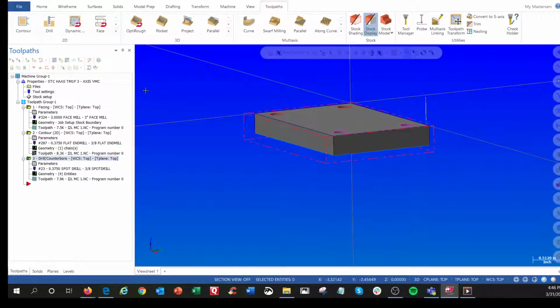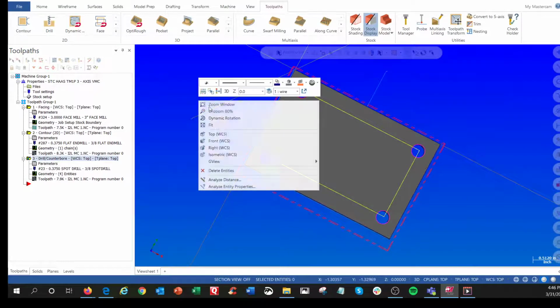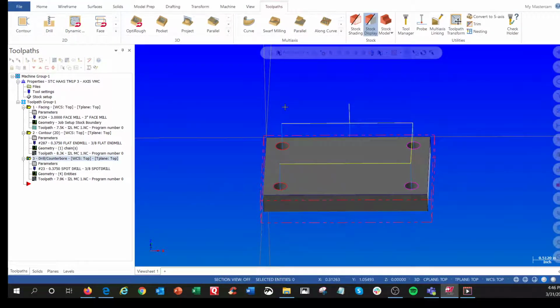Drilling cycle should be pretty easy stuff. Okay, so the first one should be pick one of the holes and get the spindle going, and then rapidly move over one of the holes and bring down the tool, and then pick a drilling cycle. One of those something in the 80s, like G81 or G82 would work.